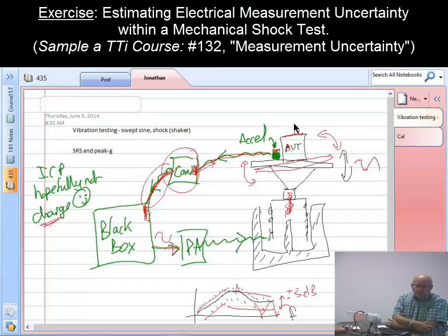And so if you've got, say, 3 accelerometers out there, you could look at 3 transfer functions and use those in the frequency domain, or you could average the 3 signals in the time domain and then calculate a single transfer function. And that would be the best estimate of the translation without rotation. Depends whether you need to look at the rotation. If you want to monitor the rotation, then you need to look at each one separately, because the difference between the accelerometers gives us the rotation, the average gives us the translation. So again, it depends what the spec's asking for or what you've been asked to do.